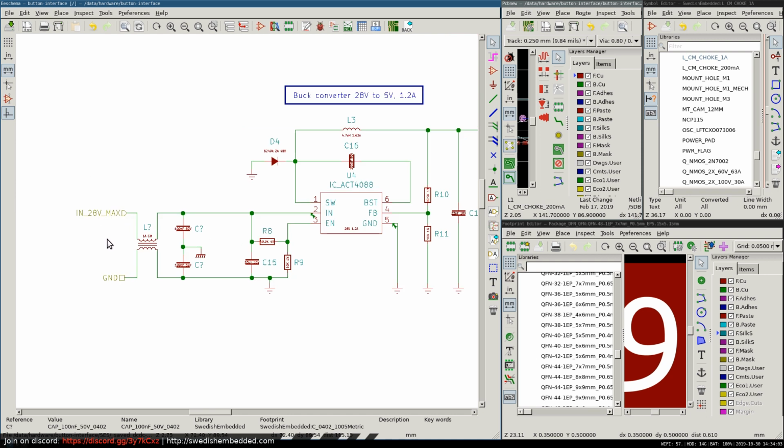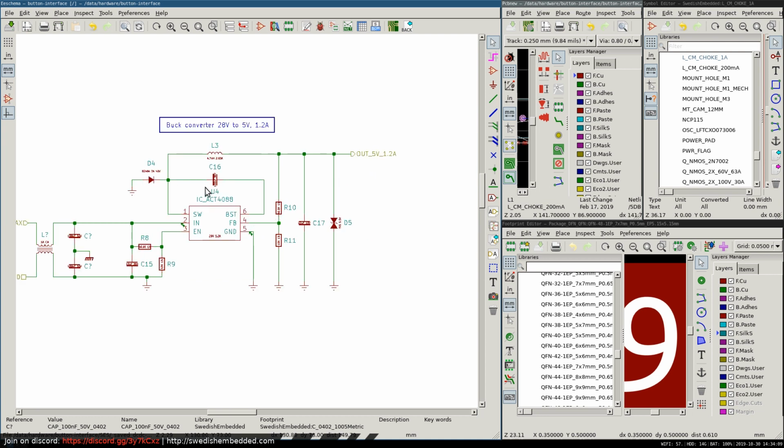When the input reaches 7.5 volts, this will enable the buck converter, which is fine because that's exactly what we want since we are getting 5 volts on the output. And I'm also placing the TVS diodes so that just in case this thing outputs full voltage, I wouldn't burn the circuitry connected to this 5-volt rail, because the over voltage will go through the TVS diode and go to ground.